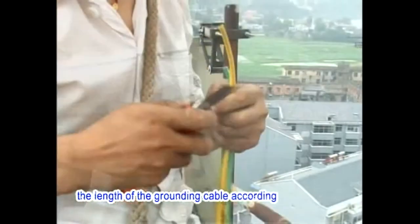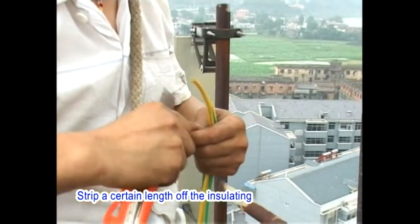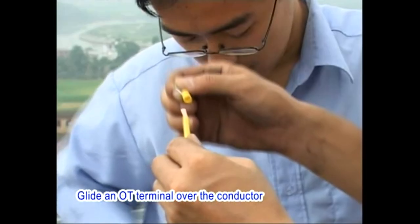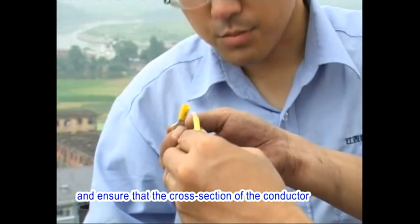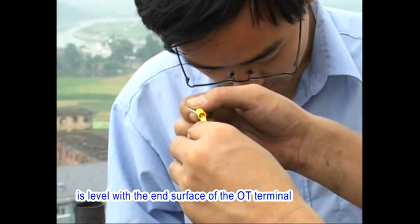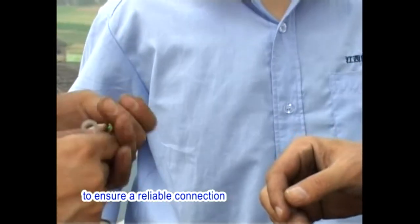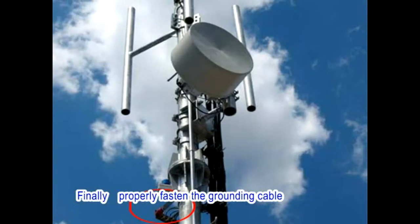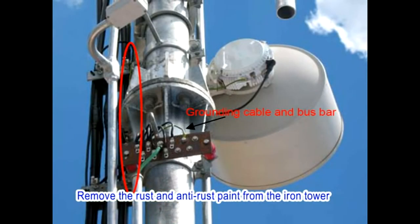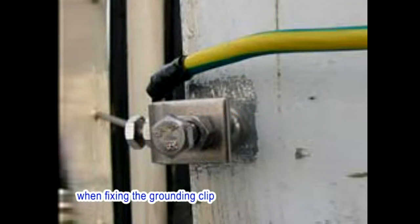Determine and create the length of the grounding cable according to the location of the grounding point. Strip a certain length off the insulating layer and expose the conductor. Glide an OT terminal over the conductor and ensure that the cross-section of the conductor is level with the end surface of the OT terminal. Use crimping pliers to compress the terminal to ensure a reliable connection. Finally, properly fasten the grounding cable to the iron tower or the grounding bar and tighten the nut. Remove the rust and anti-rust paint from the iron tower when fixing the grounding clip.